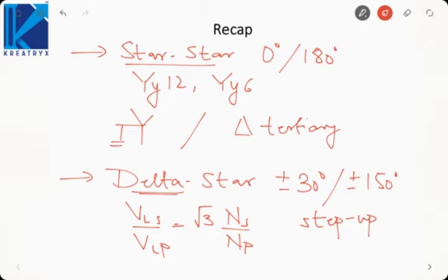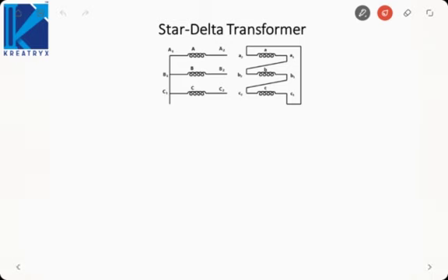In this lecture what we will be doing is we will be covering the rest of the three-phase transformer connections to complete this three-phase transformer. So let us first start with star-delta transformer. The procedure to draw the phasor diagram remains the same. First we will draw the primary phasor, and based on that we will draw the secondary phasor. Primary phasor must be drawn keeping in mind that this phase should be vertical. So let us draw primary phasor first.